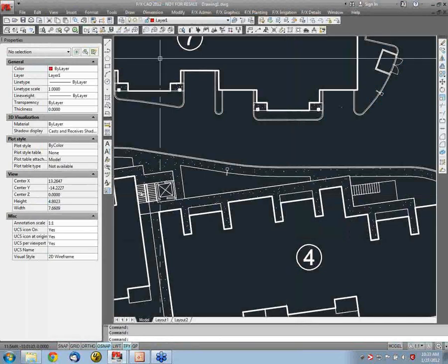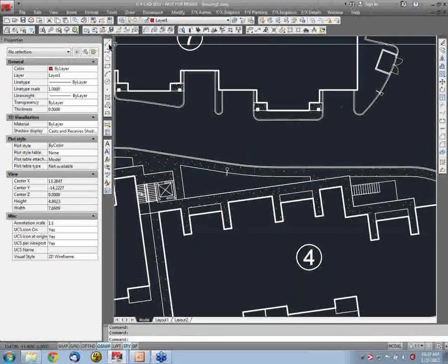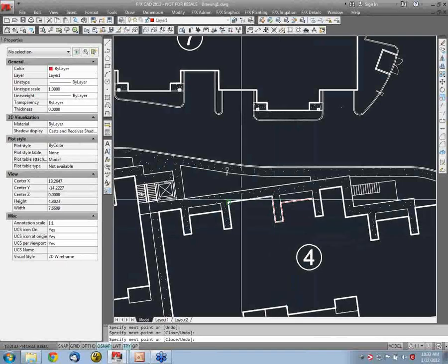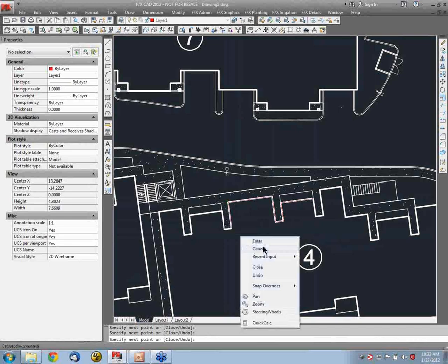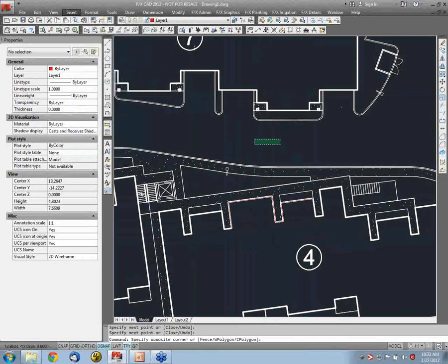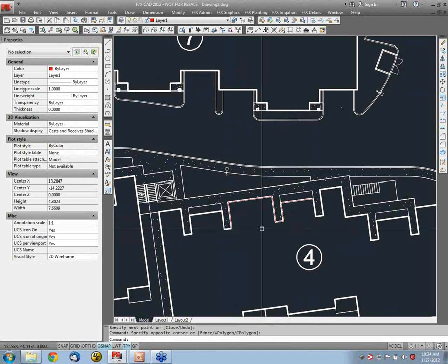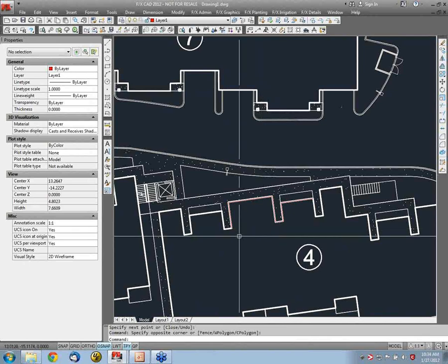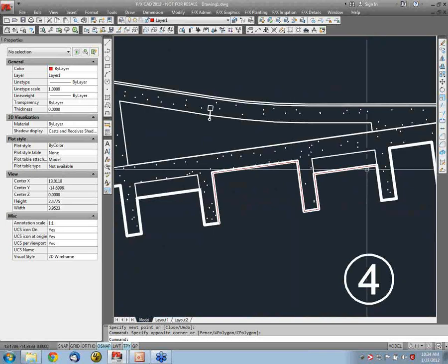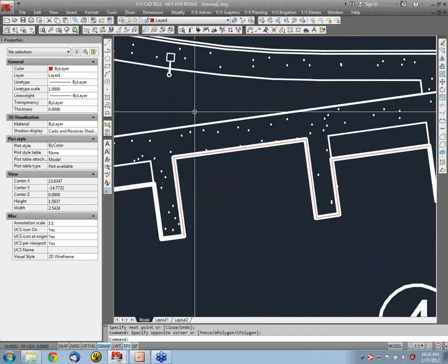But again, here I have the PDF, and I'm going to draw, and now I'm on a more visible layer here, so you can see I'm drawing a red line, and I'm able to snap to these things in here. So that's the beauty of that insert PDF underlay, it's not inserting just a picture of the PDF like the raster image, like previous versions. It was your only capability. A PDF file is actually vector. It's not just a JPEG image. It is these little vectors here that it's drawing. And so now AutoCAD has the ability to read that in, and so of course I can snap to anything, literally anything in here.